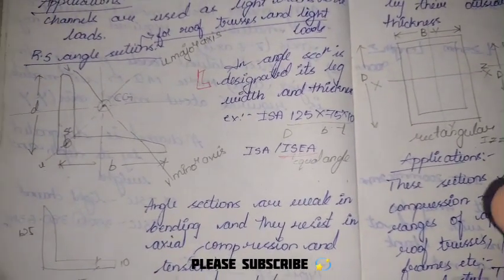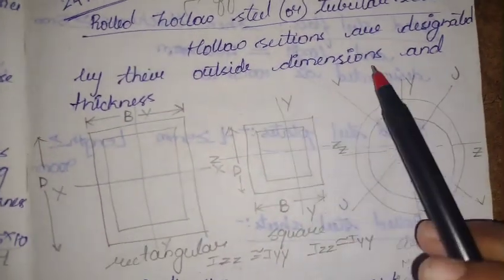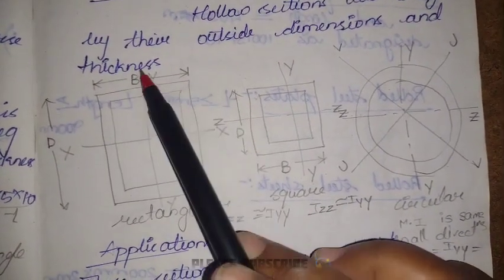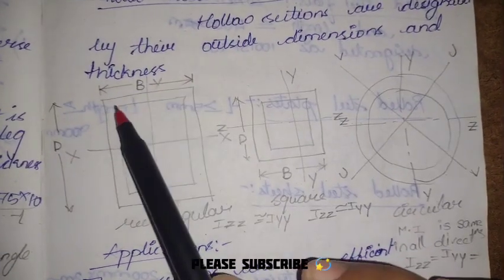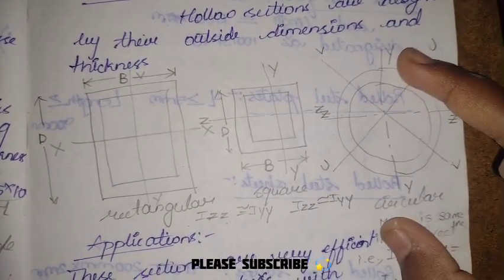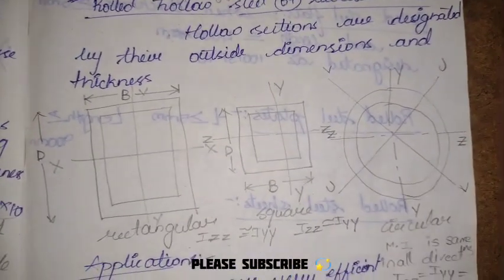Let us now see the rolled hollow steel or tubular sections. This one. The hollow sections are designated by the outside dimensions and thickness. So here the outside dimensions of this would be given and the thickness of this would be given. Depending upon this, we can just get the dimensions of the inner sections. These sections are very efficient as compression members with ranges of applications in roof trusses, purlins, in building frames. In those cases we can go with this.